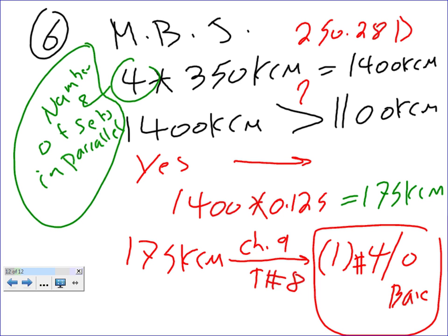No, that part I get. He's wondering, 12.5% of 1,400 is 175. Yes. So why wouldn't you subtract the 175 from 1,400 and get 1,225 and then go back to 250.66 and put a 3 on it? Because they didn't tell us to do that. Because they didn't say that you could, but the code says you take this number, multiply by this, whatever you get here is your size. Either you go custom design at 175 or you go to the next standard down.